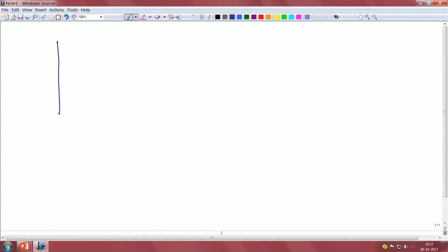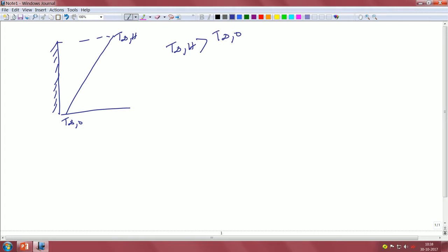So, in the last class, for understanding thermal stratification, if you recall the problem, it was still that vertical plate. One thing that happened was that the temperature of the ambient actually increased from T infinity 0 to some T infinity H, which decreases the heat transfer potential. So this is obviously going to be greater than this, and we defined parameters which convey the meaning of this.